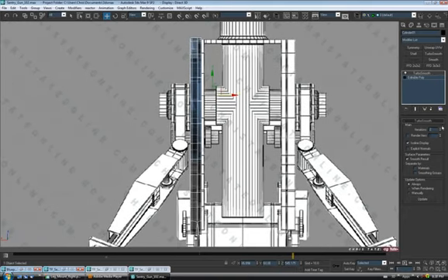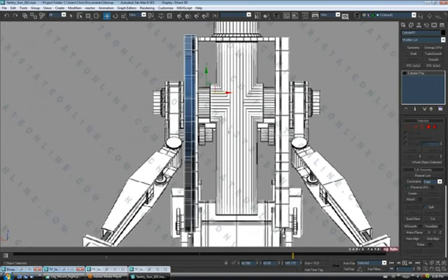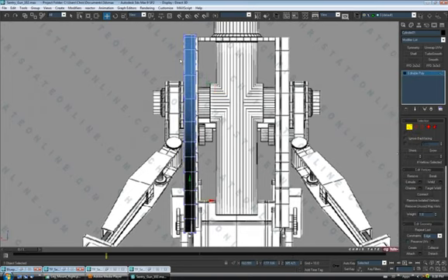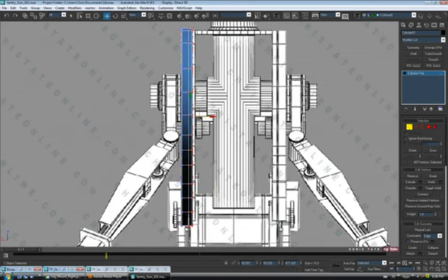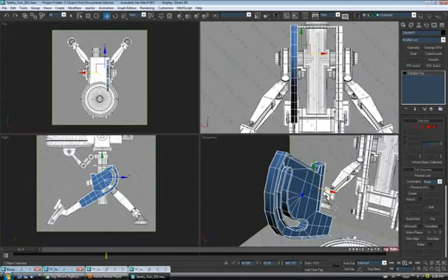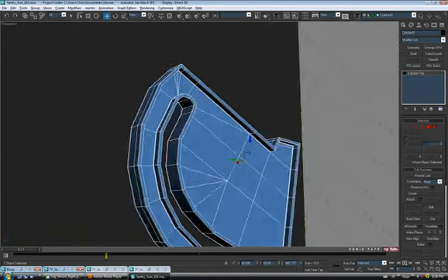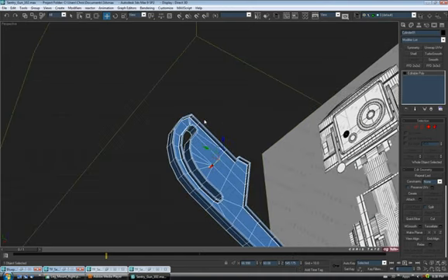So let's actually trash our turbo smooth for a second. Just get it out of the way, it's easier to see. And I'm gonna go to vertex, make sure you don't have back facing turned on. I'm just gonna grab everything on the right half of this, and we'll just move it over a little bit. And just undo that, turn off your edge constraints first. And just pull it over a little bit, and then I'm gonna hold Alt and deselect the center verts there. And just move everything on the right side over a little farther. All right, take a look, make sure we didn't screw anything up. And I think everything looks good.